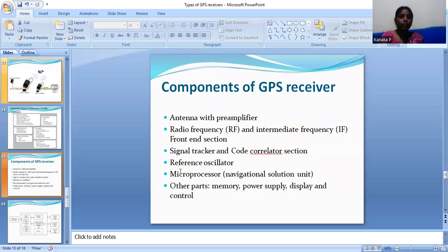So next one is the calculation. The EDM system measures the slope distance S along the carrier wave. If the instrument displays the horizontal distance H, it is because it has measured the vertical angle theta and performed the calculation. So H equals S cos theta. In a similar manner, the vertical difference in elevation comes from the calculation V equals S sin theta. So this is the electro-optical EDM system.